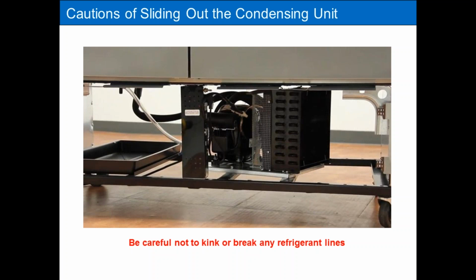But the more serious concern, and something that you really have to be on the lookout for, is when you push it back in, especially on older units. And you're going to be working on a lot of older reach-in coolers, because those are the ones that are going to fail more commonly. What you want not to happen is for the line set, either the liquid line or the suction line, to be damaged by you pushing that condensing unit back into its cavity. And it can, and it does happen.